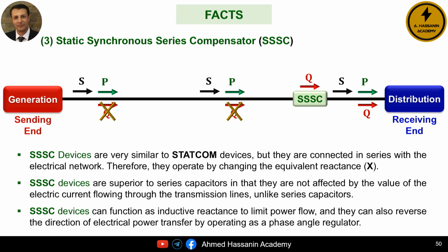Another key advantage of the static synchronous series compensator, SSSC, over conventional series capacitors, capacitors connected in series, is that the SSSC is not affected by the value of the electric current flowing through the transmission line, unlike the series capacitors, which are directly influenced by it.